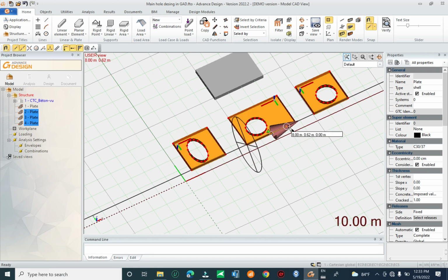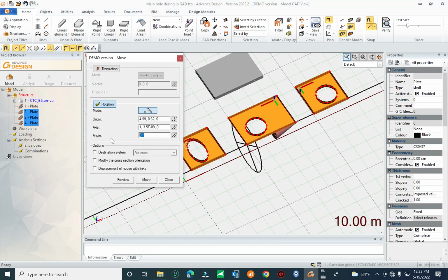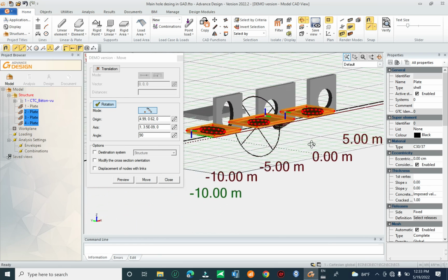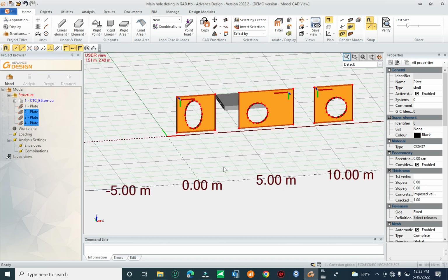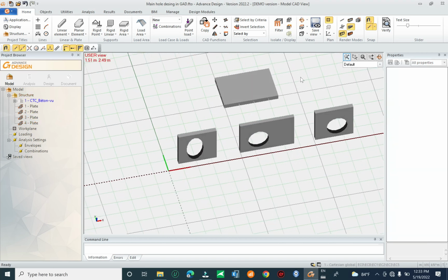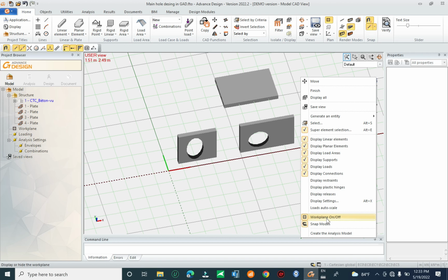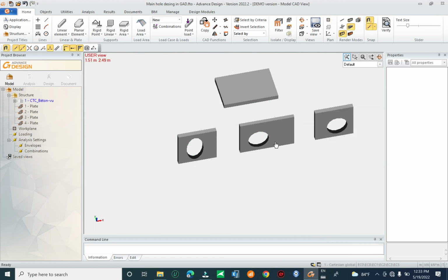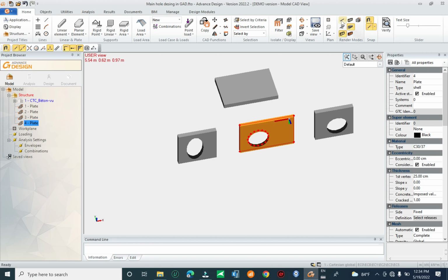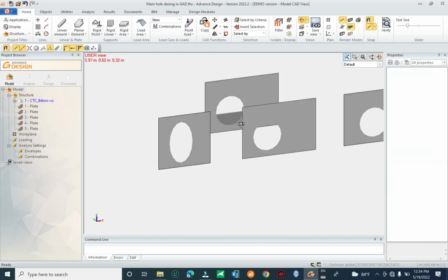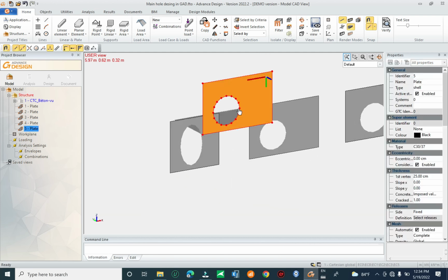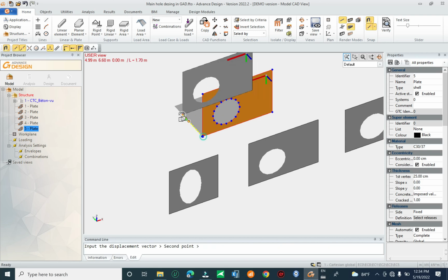You can change, okay, and the angle you can type 90 and preview and see middle key again. Okay, now see here and click on move. Okay, now indicate, click work plane on off, and after that you can click on the wireframe and control. Okay, control. If you want to copy, you can copy it, and after that we can copy to another side.